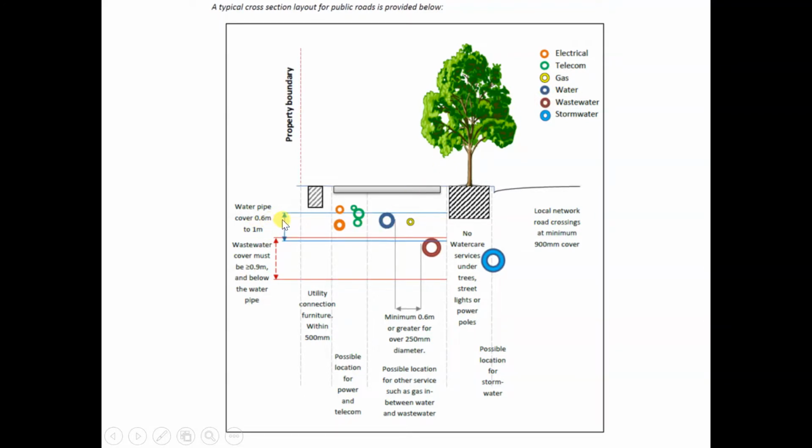It just needs to be about 0.6 meter below the ground. That's all. Even if there's a slope, the water can still go up because it's under pressure. It's not flowed by gravity. There's a water tank somewhere which provides enough pressure that the water can go up against the slope. It only becomes critical when there's a high rise. The water will not be able to reach the higher stories, so you probably need a water pump to pump the water up to the higher building.